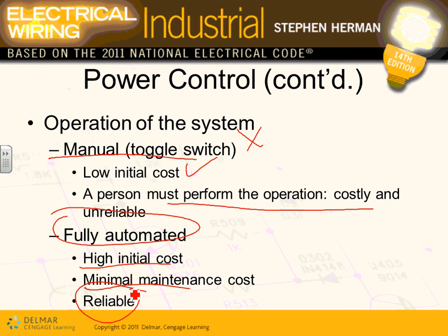So you can have a bunch of contactors, Derek, that you can drive. You can monitor your lighting system through your laptop. They have a building automation system, guys, that can monitor whether the lighting in the parking lot is on or off. So the capability is endless. When we went to Davis & Associates, I don't know if you guys remember talking about all these technologies that you can use indoor or outdoor. So, fully automated. For our project here, we use a couple of timers since we had maybe 8 fixtures outside. So we used 2 timers to control: one timer controlling the parking lot light, and the other the perimeter light.